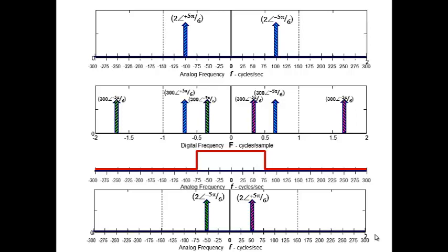So our alias signal, x_alias(t), is going to be 4 sine(2 pi times our new alias frequency, minus 50, t) and our phase minus pi over 3. Well, what we're saying is this guy aliased over to here. Right? That's what we're seeing there.